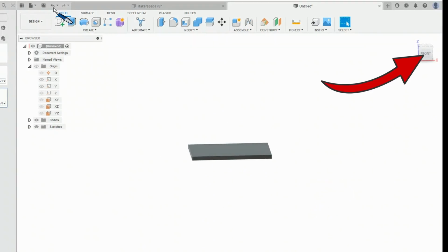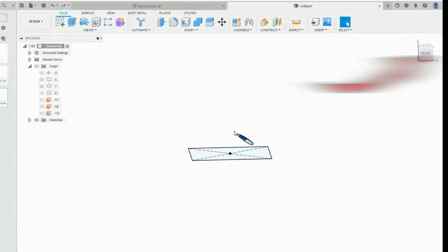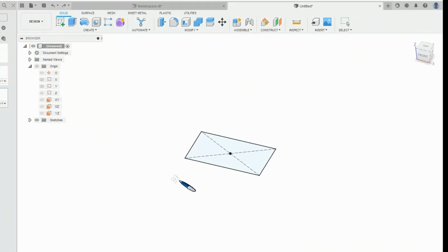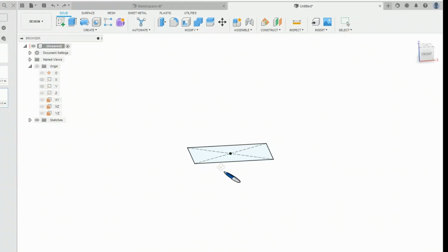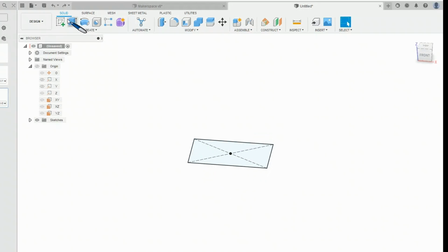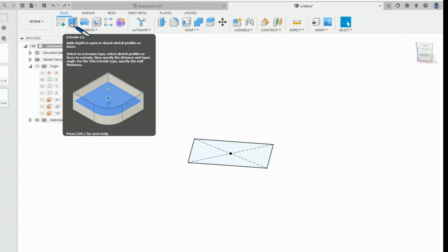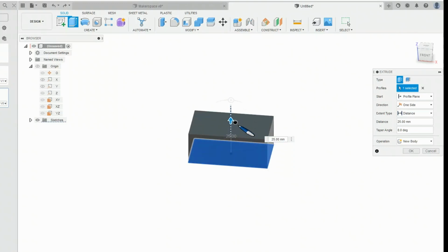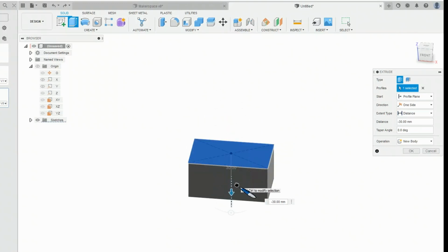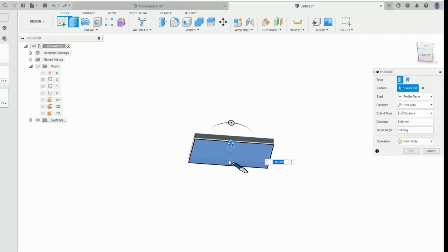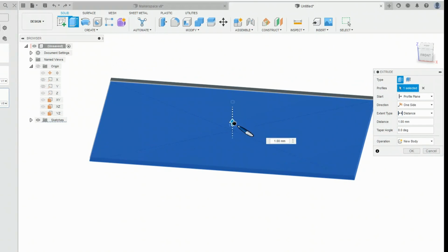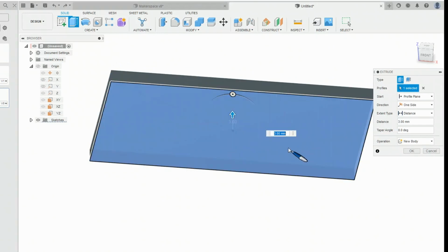But I want to undo that and show you some more detail of other options. So there you can again see my box on different angles, my flat plane. So we're going from a 2-dimensional surface and we're making a 3-dimensional surface using extrude. So instead of typing in here, I can also grab this arrow and pull it, or pull it downward, and you'll get the negative. So depending on your zoom level that you're on, you can also control quite accurately what that will be. So there's my 3mm.